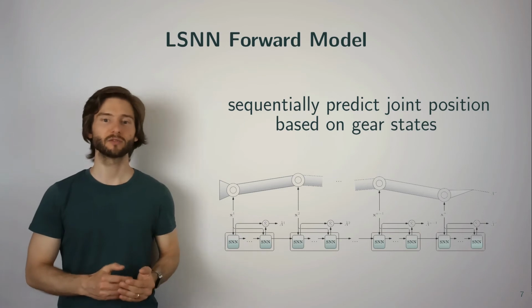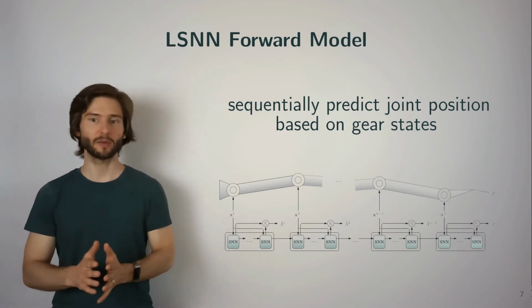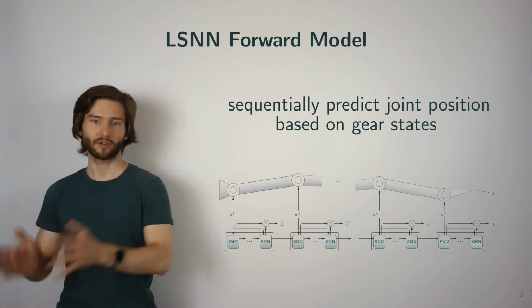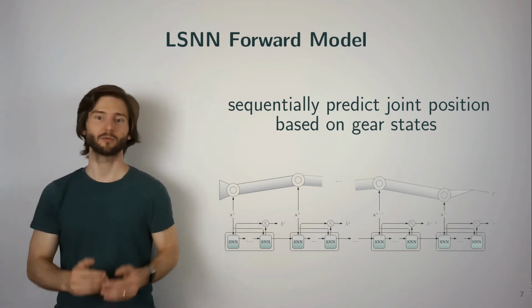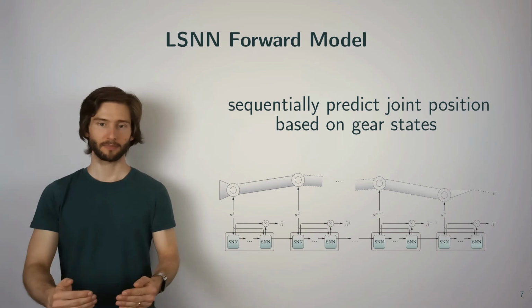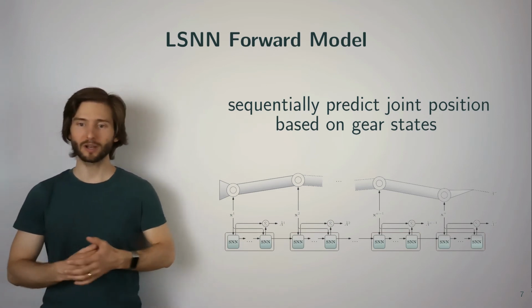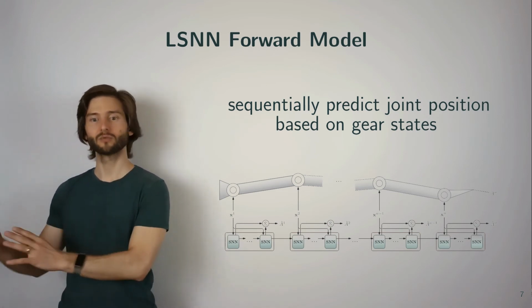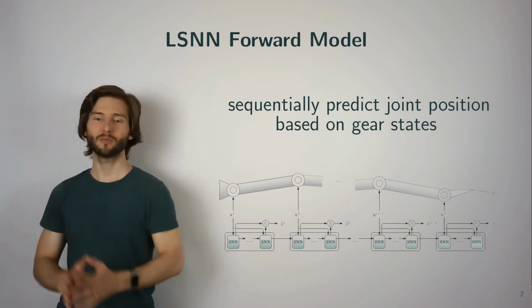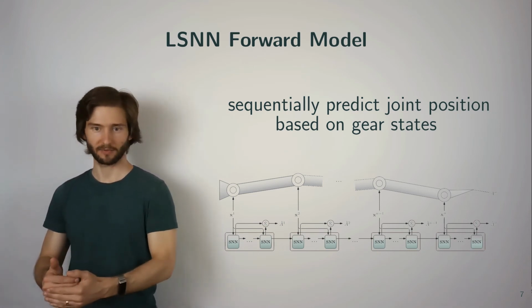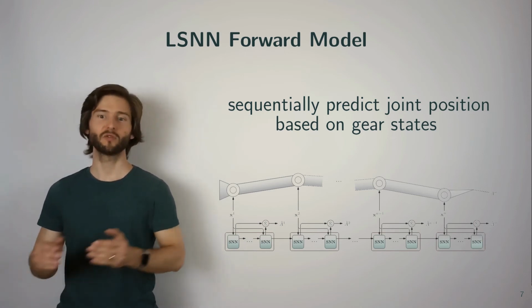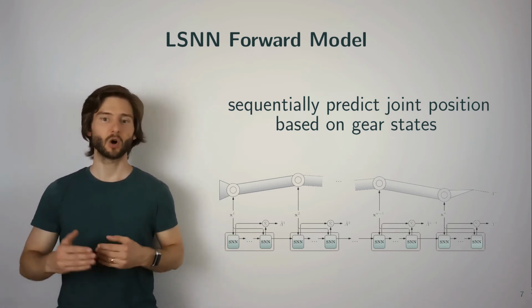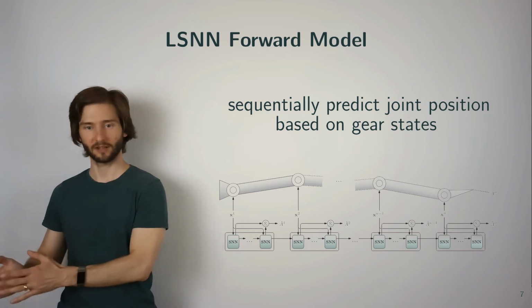And we can also do this for the orientation, where we again compare the predicted orientation with our target orientation and then backpropagate this error through the network into the inputs. Also, since we know the actual position of the simulated robot's end effector, we can perform a so-called target correction step. And here we move the target just a little bit before we compute the output error in order to correct for the prediction error of the network.